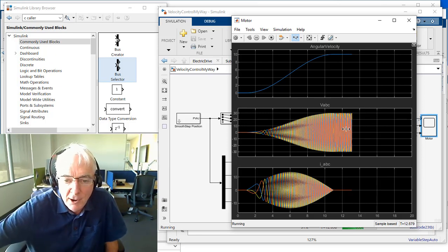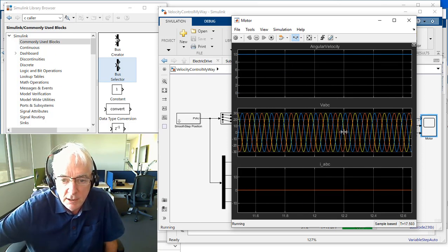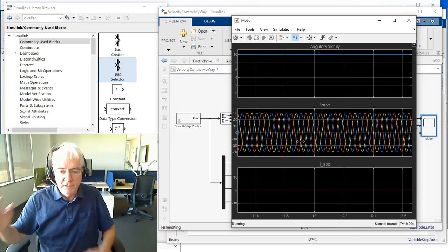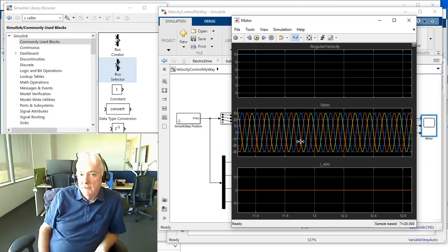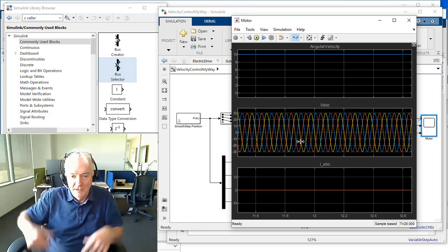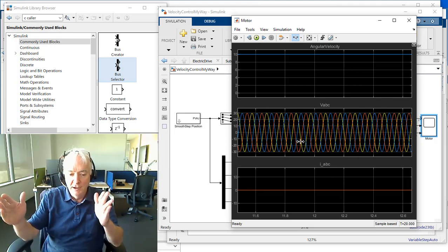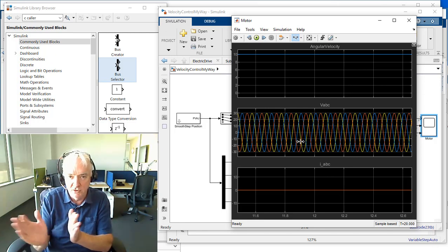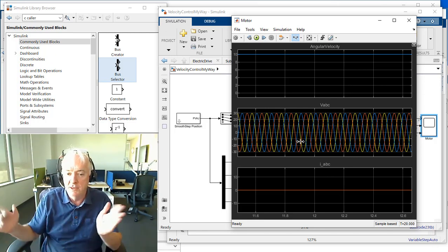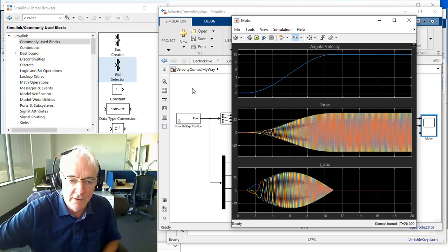And all I can say is I just kind of love looking at these AC waveforms for both voltage and current. What's taking place with a permanent magnet synchronous motor is that there are 3 voltage terminals, and they essentially control the magnetic field at certain spaces. And you get into a little bit of a conversation on what pole pairs mean and stuff like that. But from an electrical point of view, if you come up with this idea of 0 to 2 pi or 0 to 360, you can see that the waveforms are essentially spaced, let's say, 120 degrees apart from each other. Anyways, it's a very cool topic, and I might get into it in the next video where I'm going to get very specific about this.